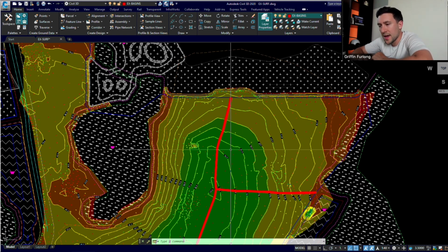So if I take that kind of approach, now I need to start thinking about where the break is between these points and which water flows to this wetland and the floodplain mitigation. And I can already kind of see it. I'm seeing a point roughly at the corner of this property line, right? Because if I'm a water droplet starting right here and I flow perpendicular, it looks like I'm going right into this mitigation pond.